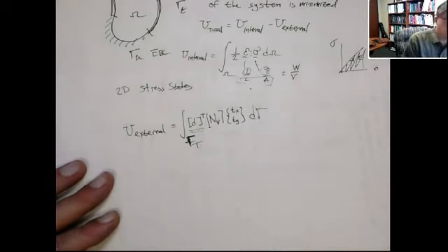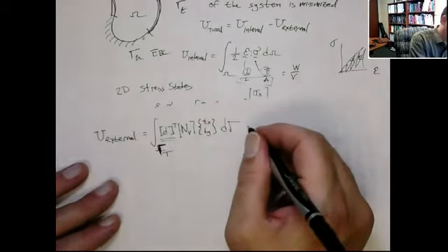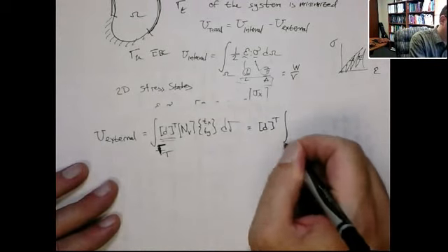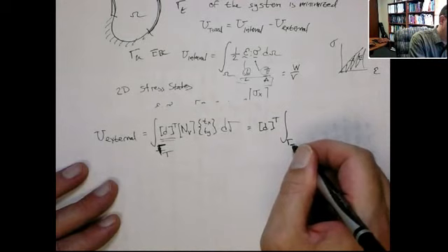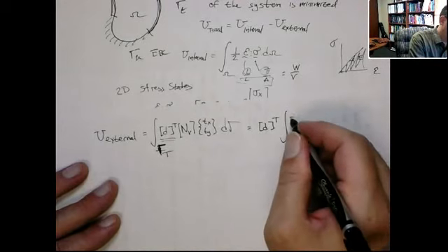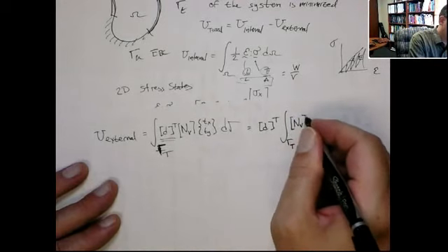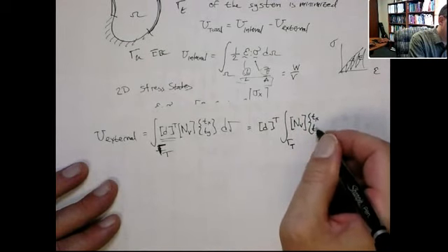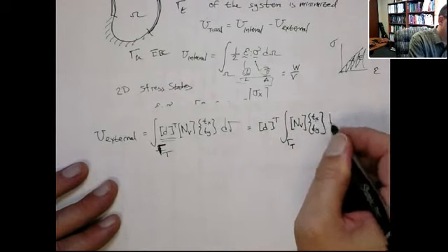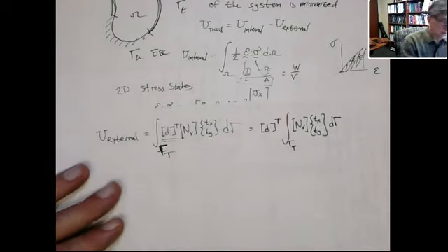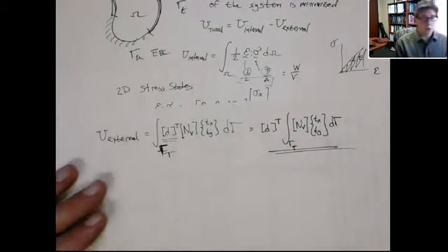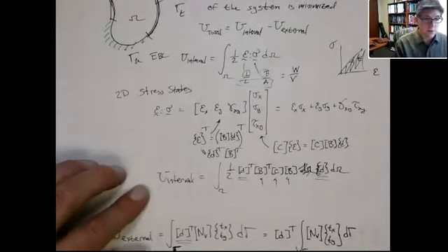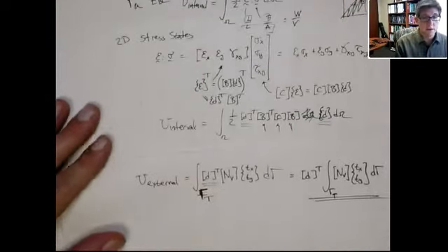Now this is a constant, it can come out, and so we just are left with d transpose integral over gamma t of this NV matrix multiplied by the tractions, d gamma, okay? So that's the work of the external forces. We have the work or the energy of the internal forces, okay?